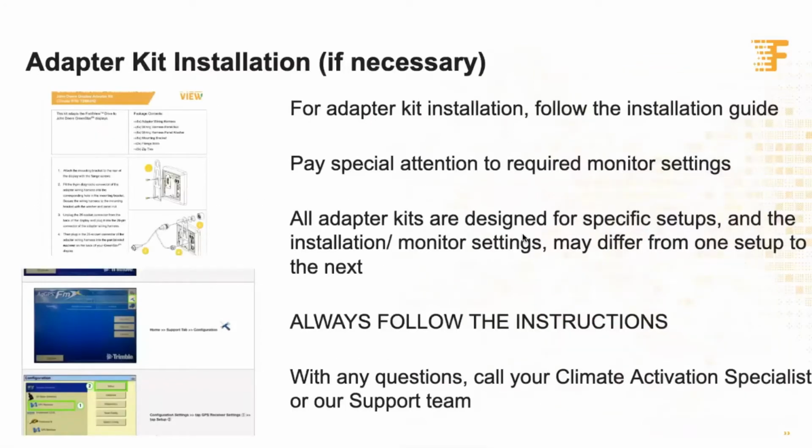So adapter kits, if you do need one, it is extremely important to follow the installation guide. They're not hard to follow. They're not daunting by any means, but they are very important still. If you have, say, an FMX in there, a Trimble monitor or something, a third-party monitor, a lot of times it's very, very important that we go into those monitors and set certain settings specifically for the drive to be able to pick up the information.